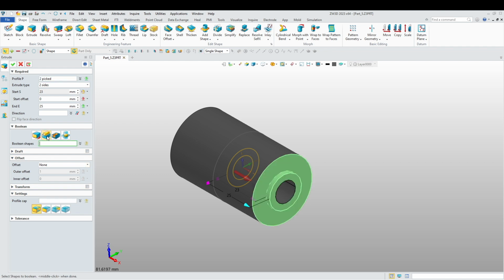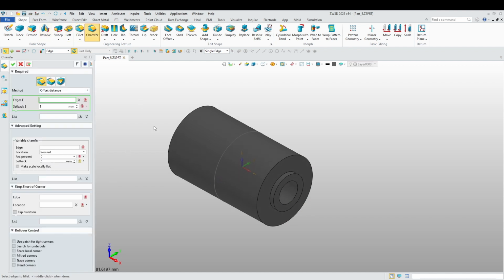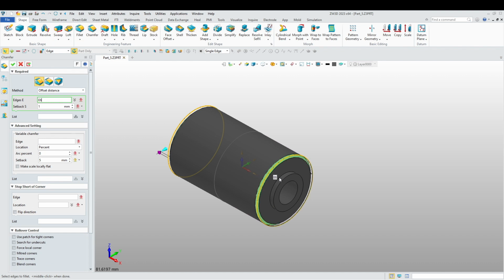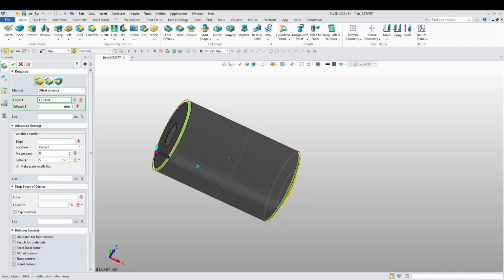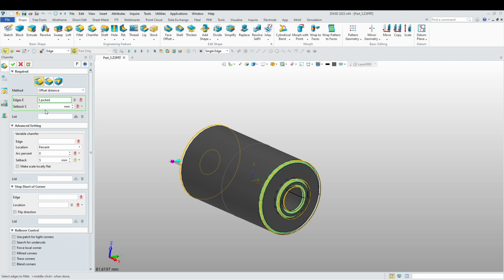I want to choose add. Here we go. And here you go. Okay. So chamfer this, this, and this hole. 0.5.